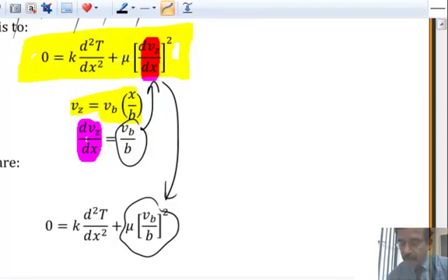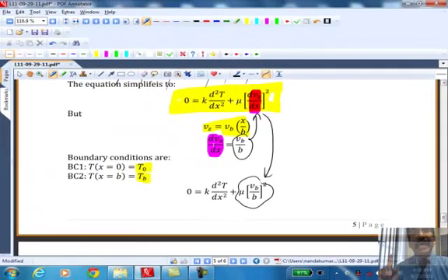What does that do to the velocity profile? The velocity profile will be influenced by the temperature profile, because the temperature profile will influence the viscosity, and the viscosity will influence the velocity profile. So we would call that kind of problem a fully coupled problem, because velocity influences temperature and temperature influences velocity. They both depend on each other. That means the energy equation has viscosity and the gradient of the velocity in it, so the temperature will depend on that.